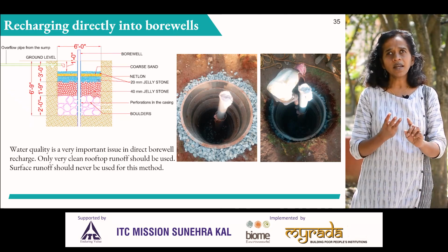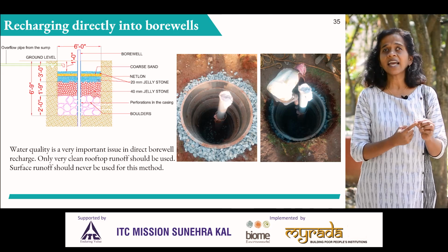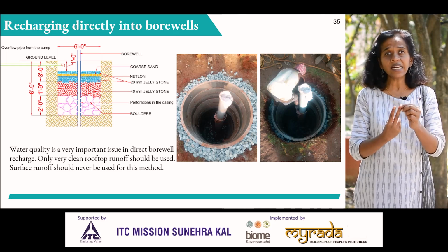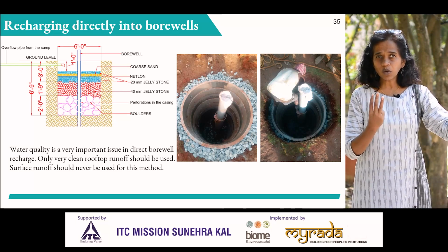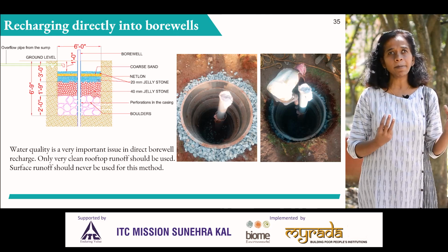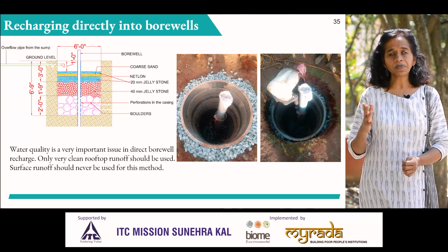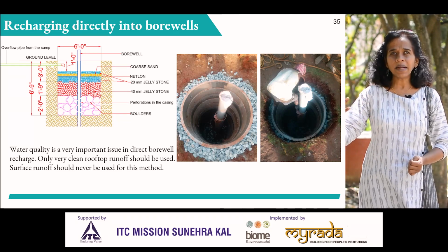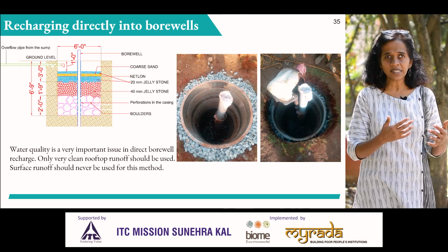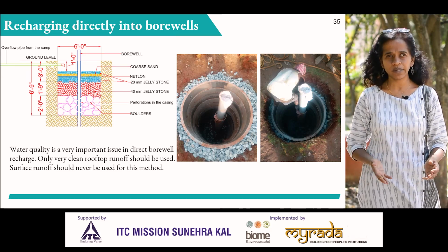Some things to keep in mind: do this kind of direct borewell recharge only for borewells which used to yield and have now gone dry. It is preferable that you don't do it for a borewell that is currently yielding. Remember, whatever is the quality of water that you put into this direct borewell recharge is the same water that will come back to you. Here there is no possibility of the ground further filtering your water, which is why sometimes recharge wells are better dug in public places, because we may not always have a control on the quality of water that is coming in. Here the weathered soil plugs in to help us because it is able to filter the water.